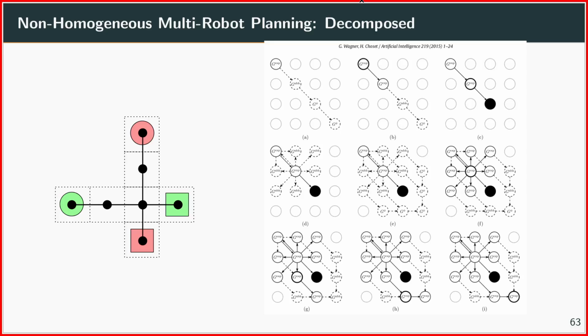In this case, you choose this one here, and then again you just execute the path until you reach your goal region. And so in this case here, you have moved both here to the second step, and then one of the robots just stays here while the next robot is actually moving to the goal, and then the path is free for the remaining robot who moves to the goal. So very similar to conflict-based search, but applicable to a very general graph structure for each of the robots.